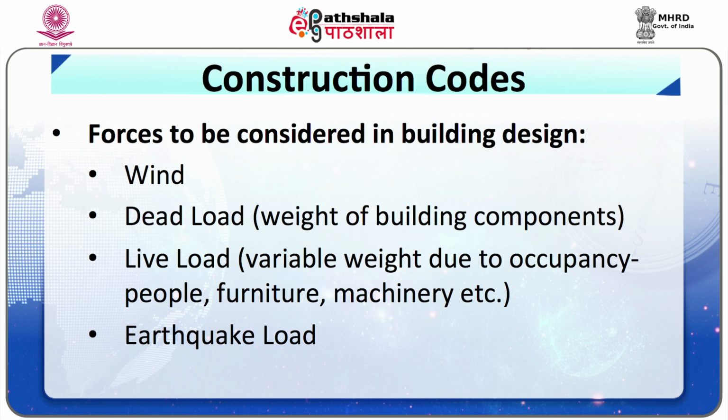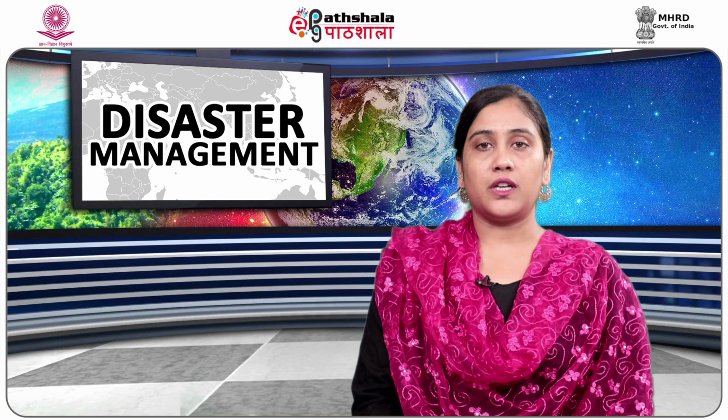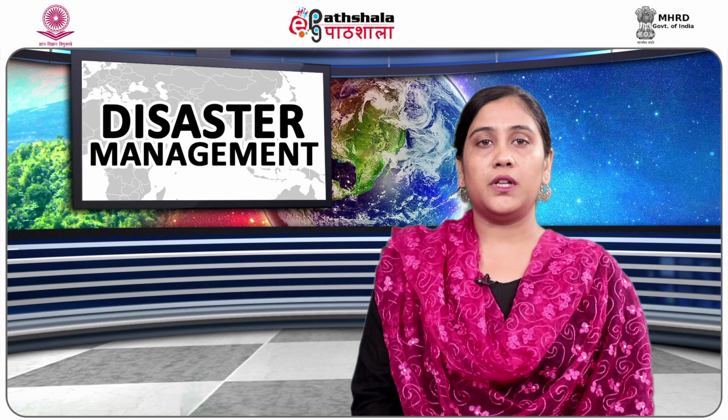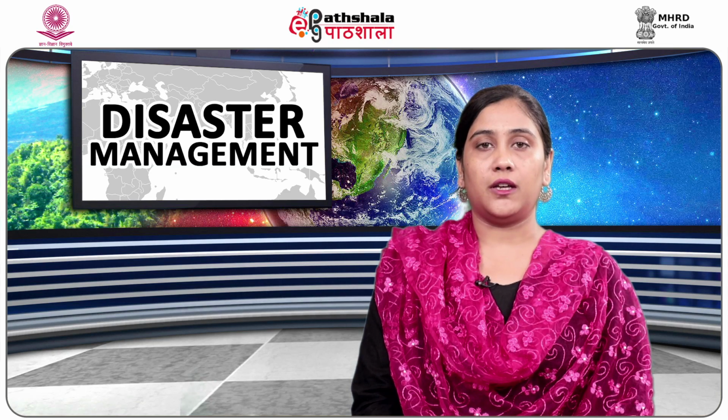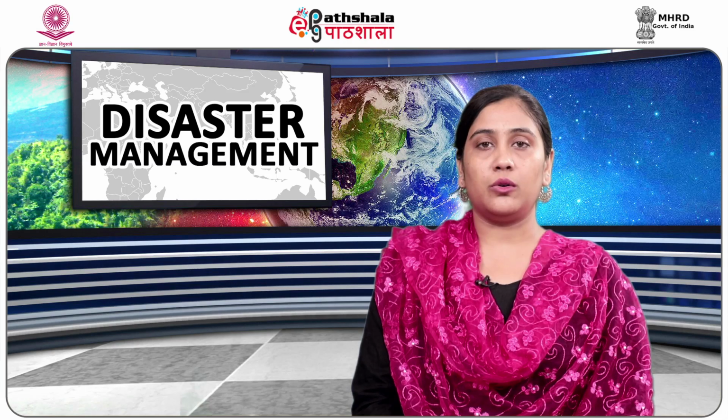Construction code: any building must consider the following forces: wind, dead load, which is the weight of the building components, live load, the variable weight due to the occupancy like people, furniture, machinery, etc., and earthquake load. The building must stand stiff under normal conditions by taking into consideration the first three loads, while during ground shaking associated with an earthquake, the building must be ductile enough to dissipate input energy and not collapse completely. The extent to which the building must be ductile would depend on the location of the building and the geological constituents of the ground in these locations.